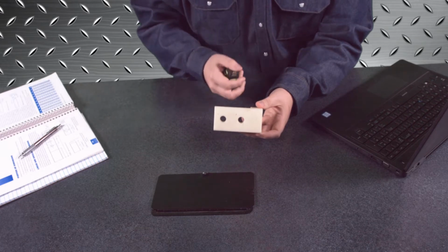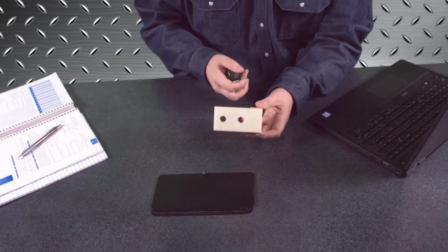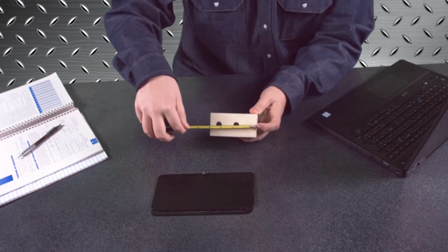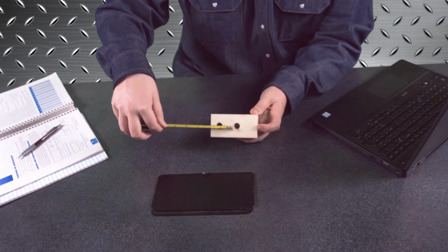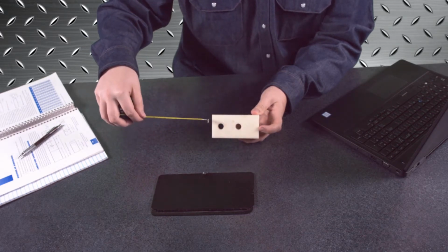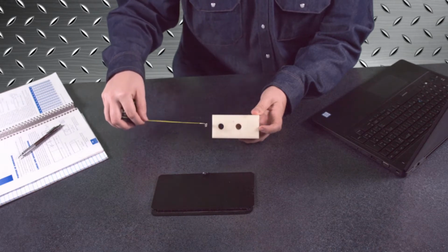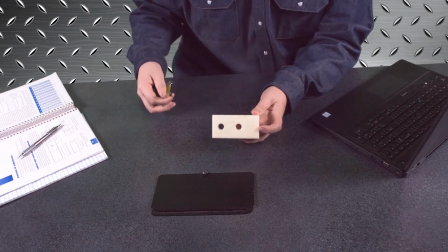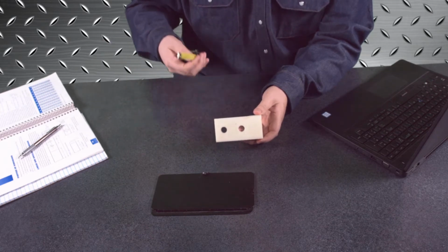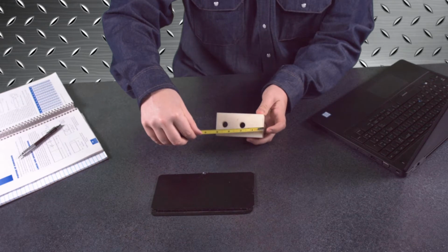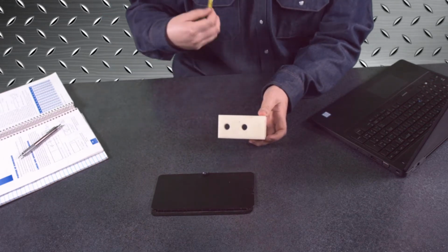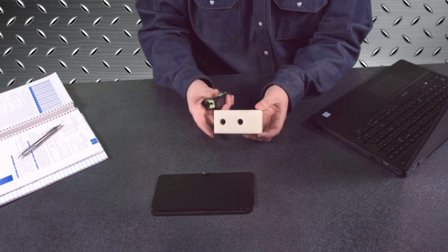But baseline dimensioning I consider to be far more accurate than conventional dimensioning, because with conventional dimensioning, you can take this measurement, move on, take the next one, move on, take the next one, move on. Across this whole part, you took 4 separate measurements from 4 different points, and if you have a slight error in each measurement, over time that error will build up in a cumulative error. With baseline dimensioning, you're always drawing from one point, so it'll be a lot more precise. You have less chance to introduce error into your measurements whenever you're building something.